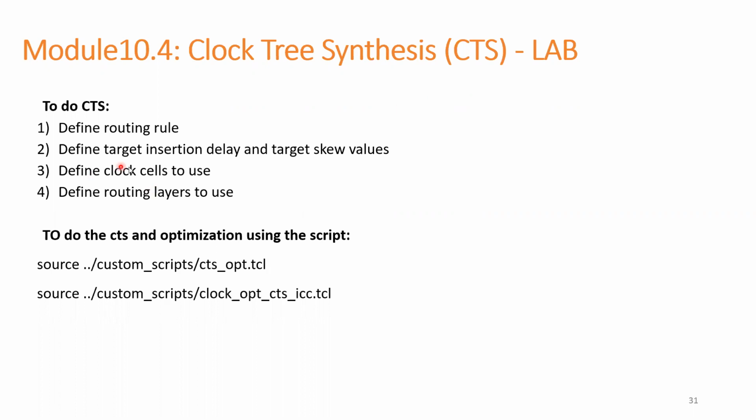Insertion delay target to a sink pin also we can give. If there is any insertion delay target requirement, we need to give it, and skew targets also we need to give. So this is about skew.